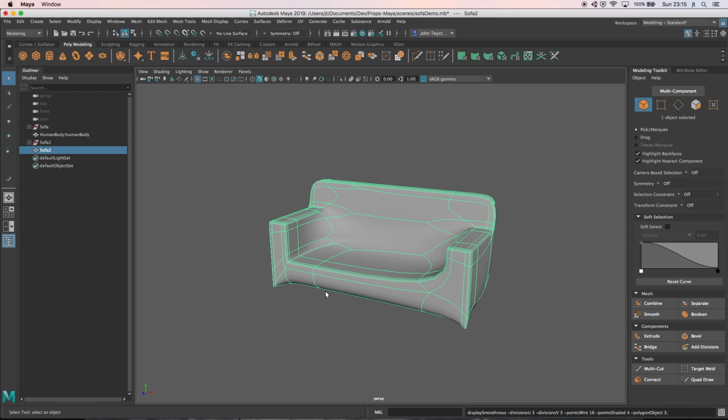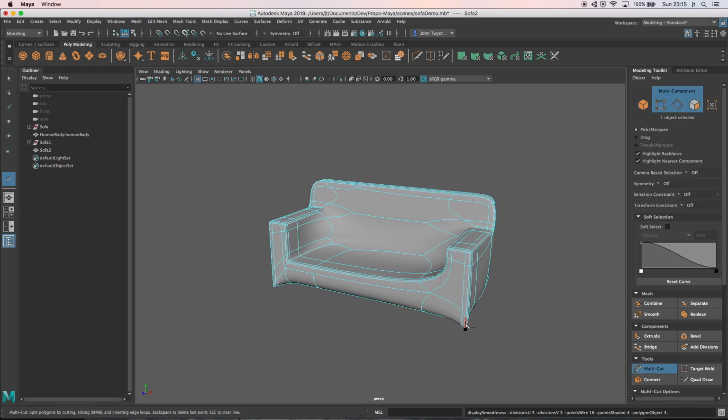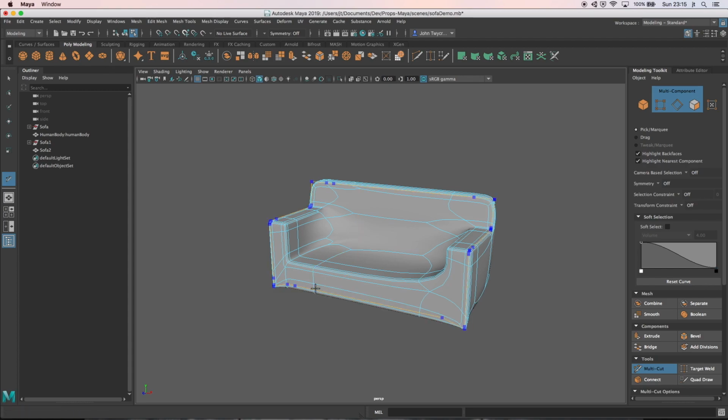And if I add an edge loop around the bottom, I can actually do it while it's live. So I'll use the control key and add extra geometry in there, and that will start to straighten those out. And you can see there it's come in and become much straighter. So adding in these extra bits of geometry really straightens the bits out.